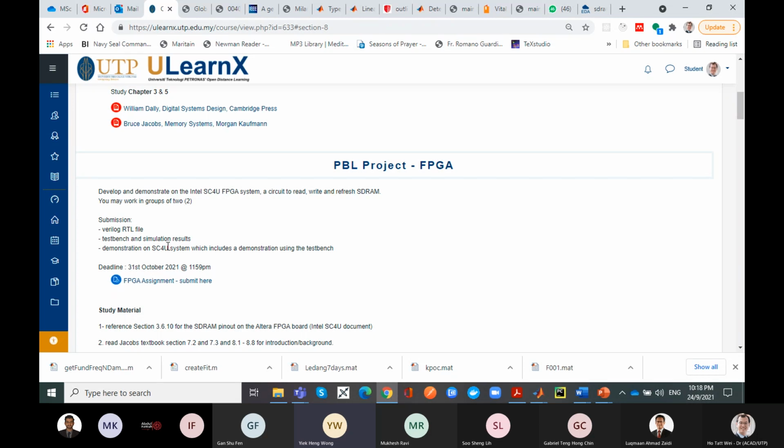So which one should we use actually? Okay, Yaking, let me clarify this. That's a great question. SystemVerilog is a newer version of the Verilog standard. There are certain additional keywords, and one thing that is very powerful about SystemVerilog is the testing and verification setup. The way you can write test benches, it has a lot of extra syntax for assertions, assertion checking, as well as transaction-based checking.